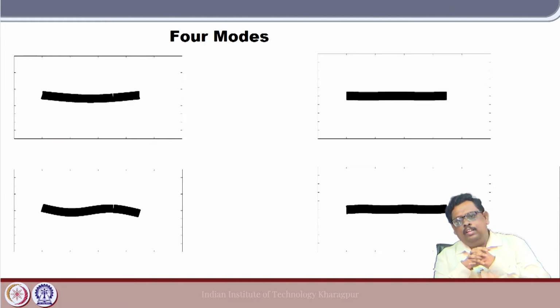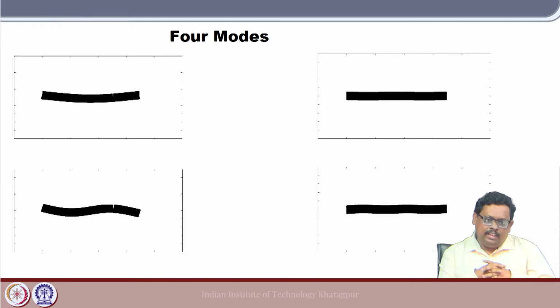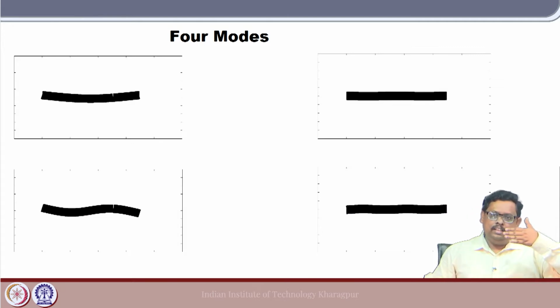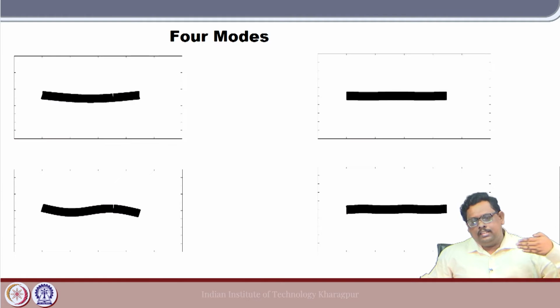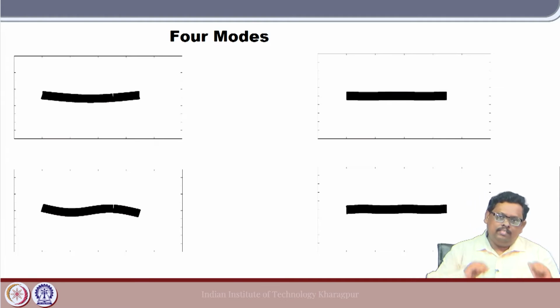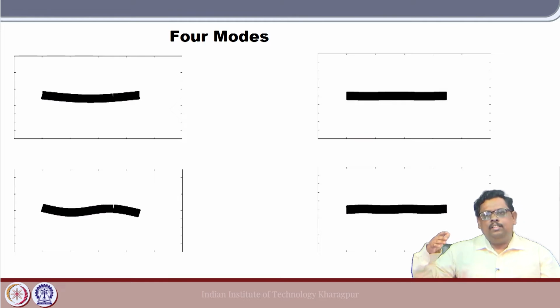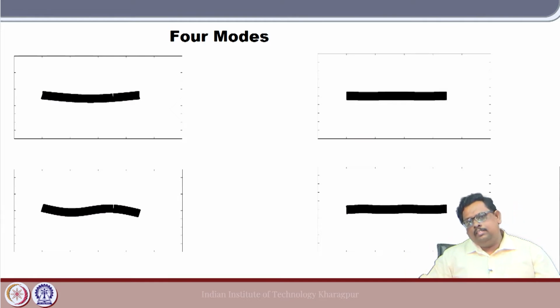If you remember the rigid modes, we know that we have 6 degrees of freedom. The structure can only oscillate in surge, sway or heave, or in pitch, roll and yaw. In the case of a flexible structure, it can oscillate in infinitely many different ways.